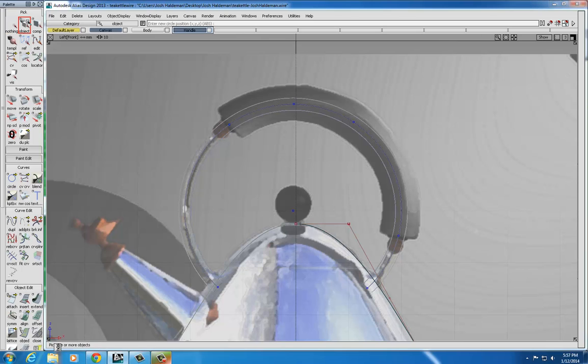I'm going to go to Pick Nothing, Pick Object, select the arc, and assign that, the original 3-point arc, not the new one I just finished, but the original 3-point arc. So make sure you click outside of where the grip is. Go to the handle layer and assign it there. What that'll do is ensure that I've got just the new 3-point arc on. Everything else is on that handle layer and is set to inactive.